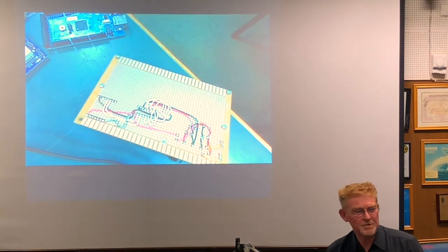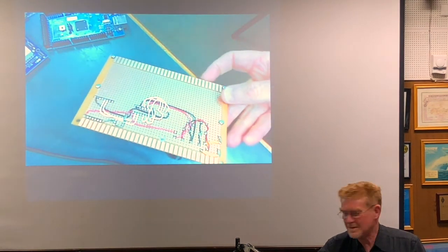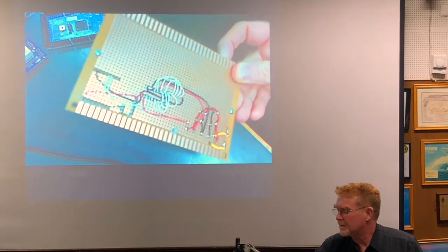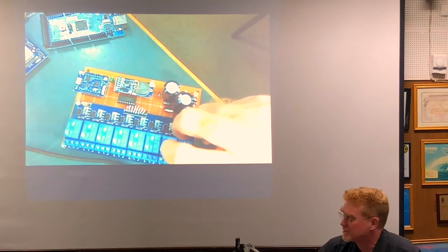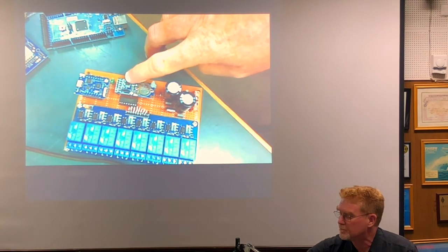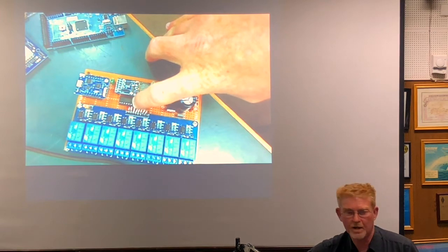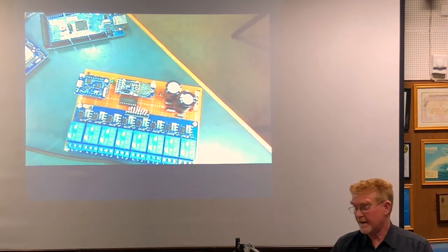It doesn't have very many pins to work with. But the I2C bus, because it's a serial bus, it's worth understanding because it can talk at the same time to that clock module and this guy here, which is an I/O expander, which is driving the relay control board. I can add more of these.